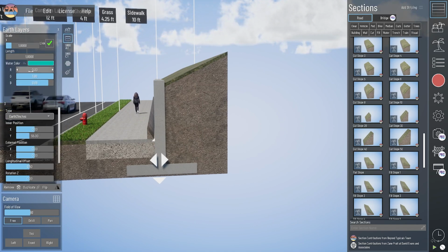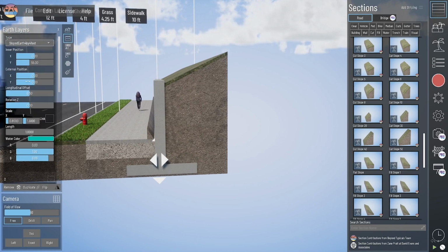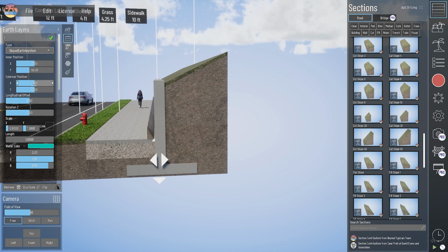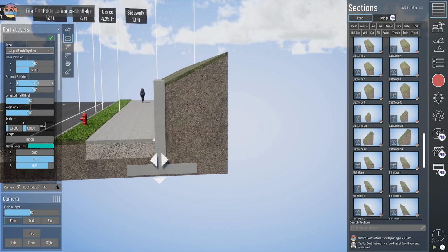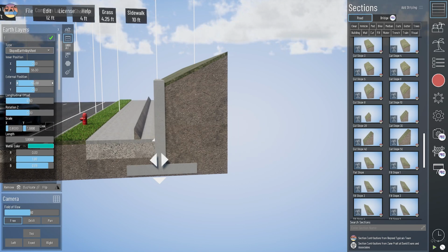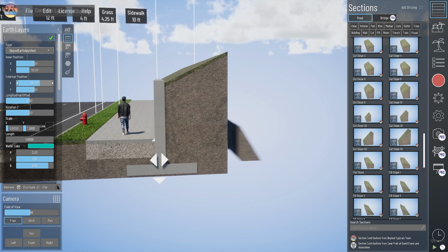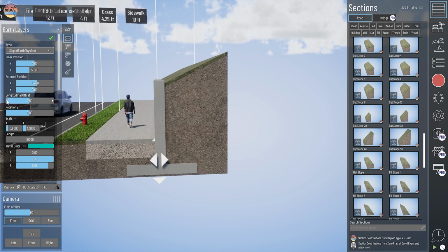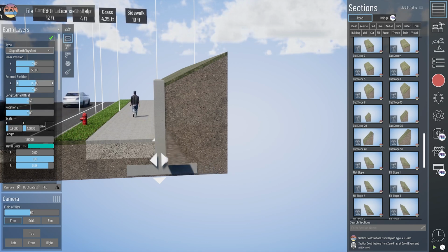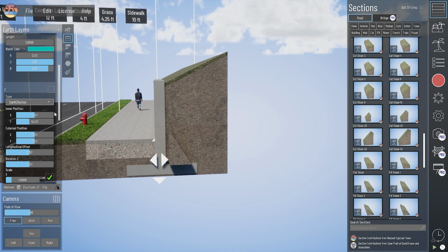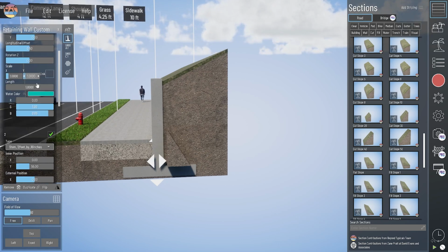And if I move that piece around, I'll be able to adjust where it shows up with respect to that section. And then you'll see that it is being hidden. So what I'm going to do is move this longitudinally forward by 0.1. So now I can see that element here, and I'll do the same with my retaining wall just to have that all look appropriate.